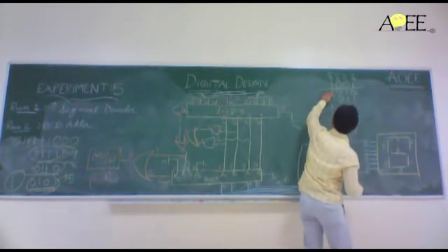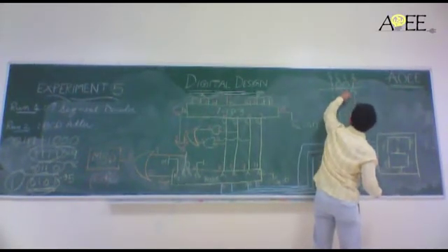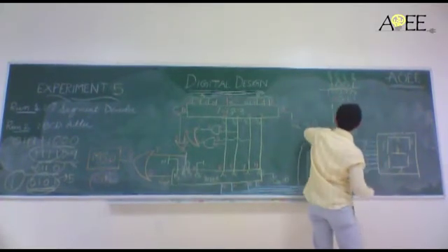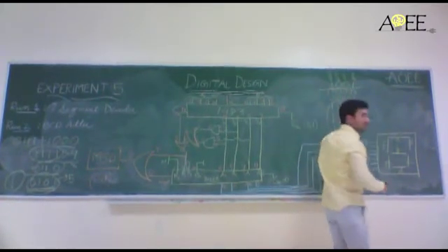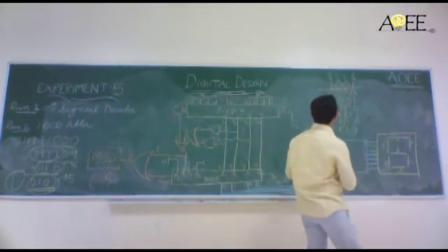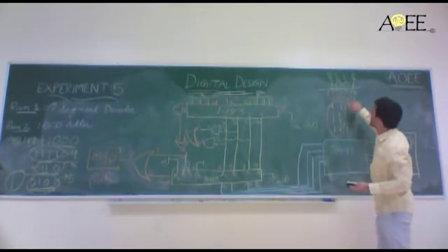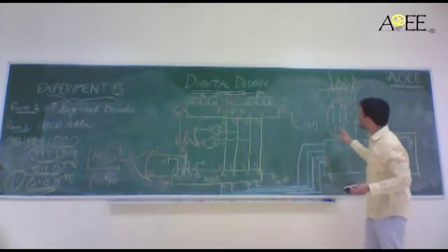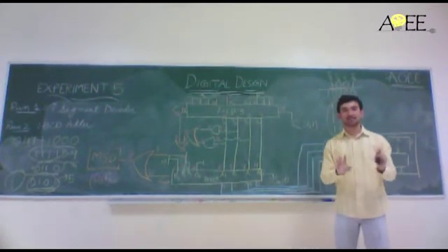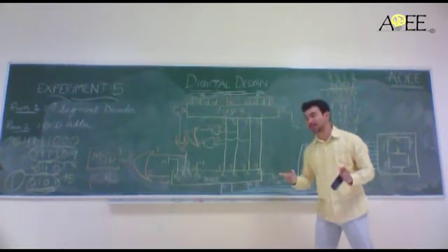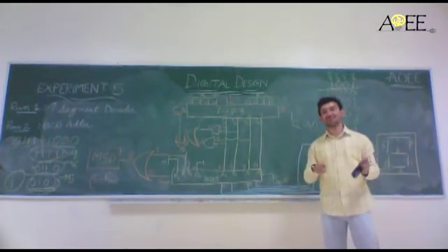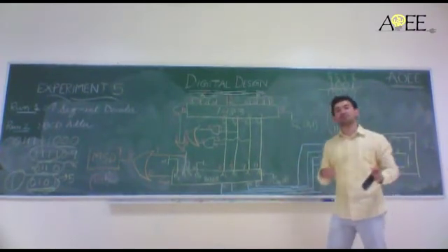Okay, so just have a look, leave 9. In these two cases, S1 and S3 are 1, and in these remaining cases, S3 and S2 are 1. So I can say that when S3 and S1 become simultaneously 1, then I have a number greater than 9. I can also say that if S2 and S3 simultaneously become 1, then I have a number greater than 9.